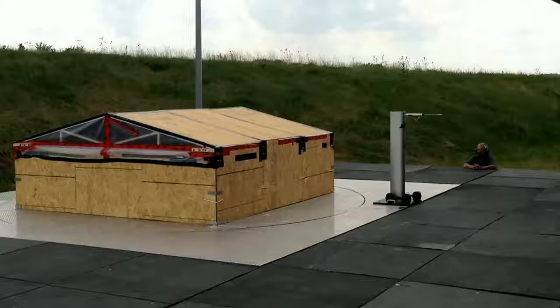In the following video, evidence of 3 distinct stages of failure will be visible. In order, these stages are initial displacement of the roof-to-wall connections indicating net uplift, initial full withdrawal of a single roof-to-wall connection, and lastly, full withdrawal of all roof-to-wall connections.